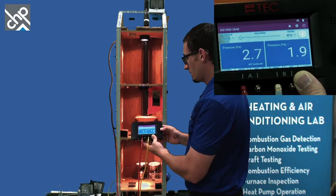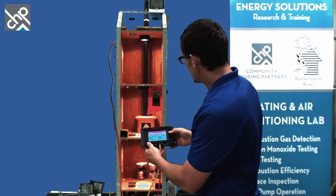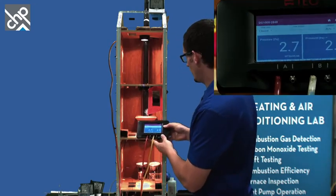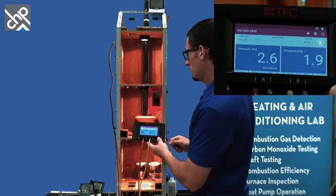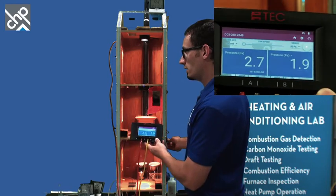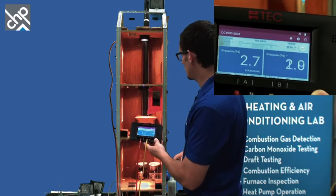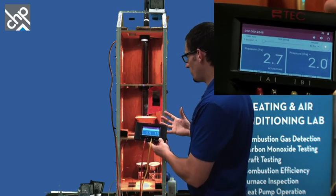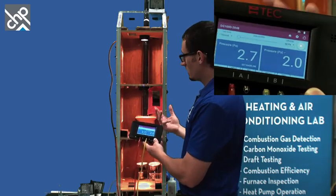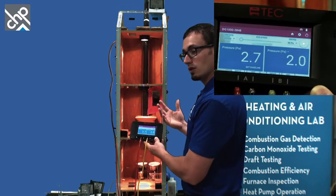Positive. Positive throughout. What's happening with my smoke? So now I can see that my building pressures are going positive. My smoke is kind of kicking on here. I may have actually turbocharged my wood stove here. It's kind of kicking, screaming. You guys see how fast that's moving up and out of the house. But I've positively pressurized the building, so I'm no longer backdrafting. I might be burning more wood, using a little bit more fuel, but I'm not actually backdrafting anymore.